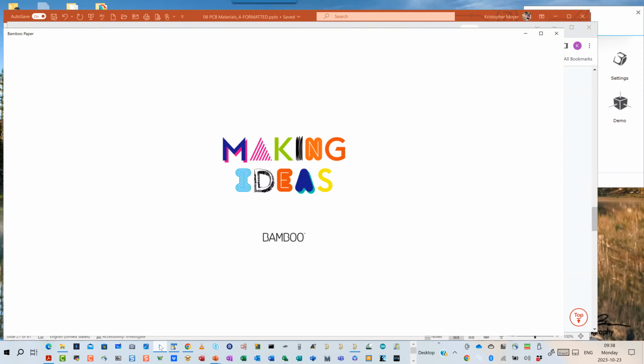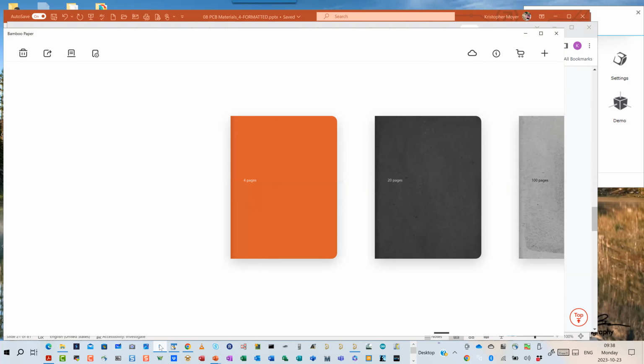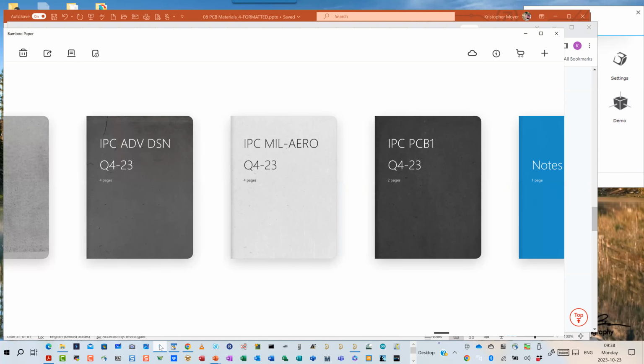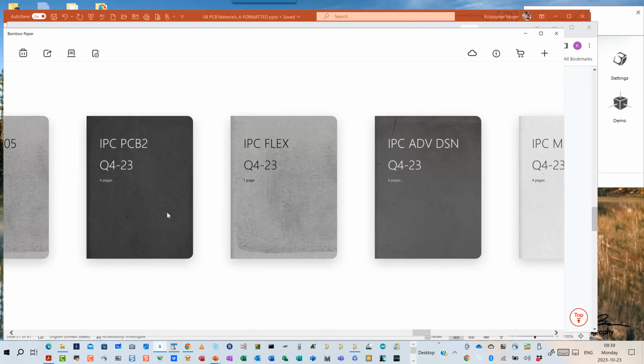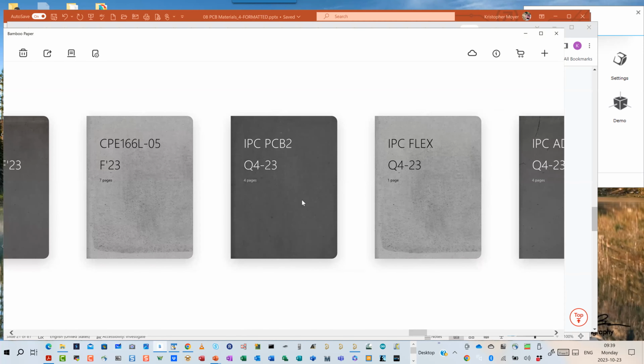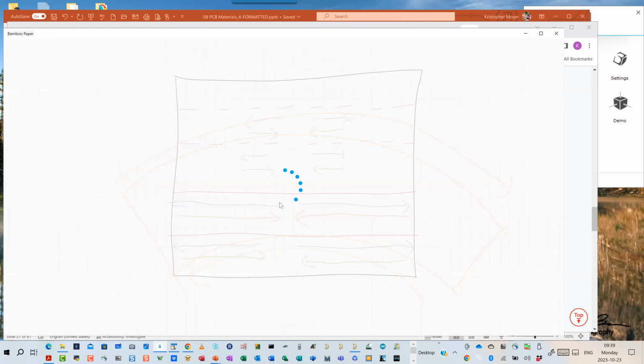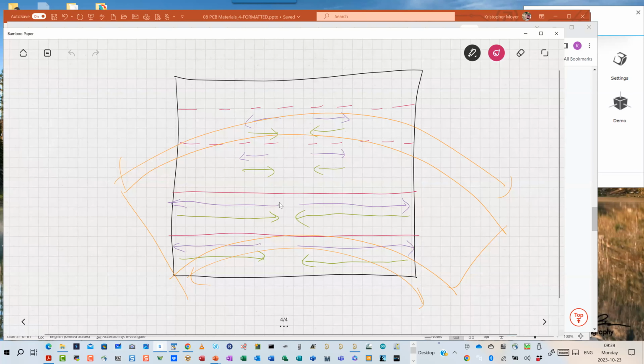So I know there's like a standard, while you're drawing. There's a standard that talks about, I think it's in aerospace, that usually the dielectric layer between the first and the second layer has got to be a minimum of like 3.5 mils. Is that what it's accounting for? What IPC says is, when you as the designer do not specify it, that's the minimum they will use.